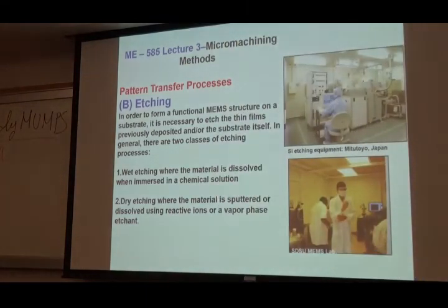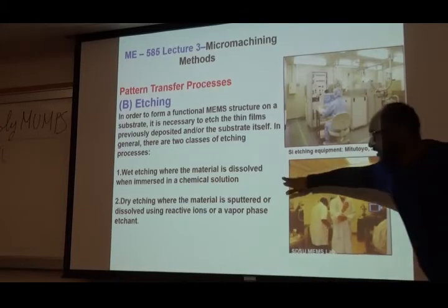What's the etchant that I'm going to use? I've mentioned it since day one. KOH. Take that, put it in KOH, just in a buffer. You'll be surprised, the kind of container that we use is just like that lunchbox, plastic, because the acids and the bases don't attack plastic. So you put it there, it waits for an hour, half an hour, whatever, and it etches away the silicon. So that's called wet etching.